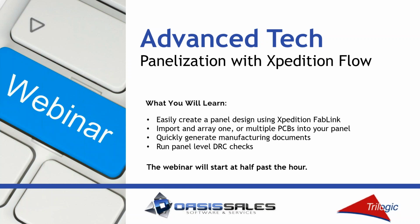After we talk about that, we'll just talk about how we can array multiple PCBs onto the panel. Xpedition does have the ability to do multi-board panels. And then we can go ahead and run some panel level DRC checks and then generate manufacturing documents.